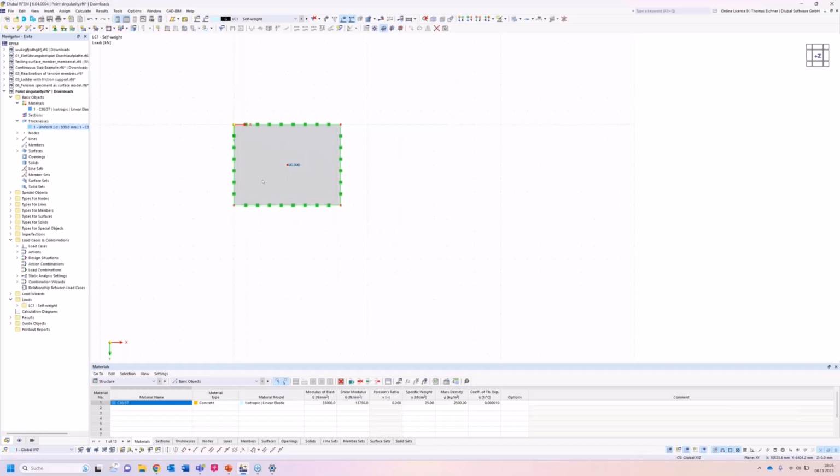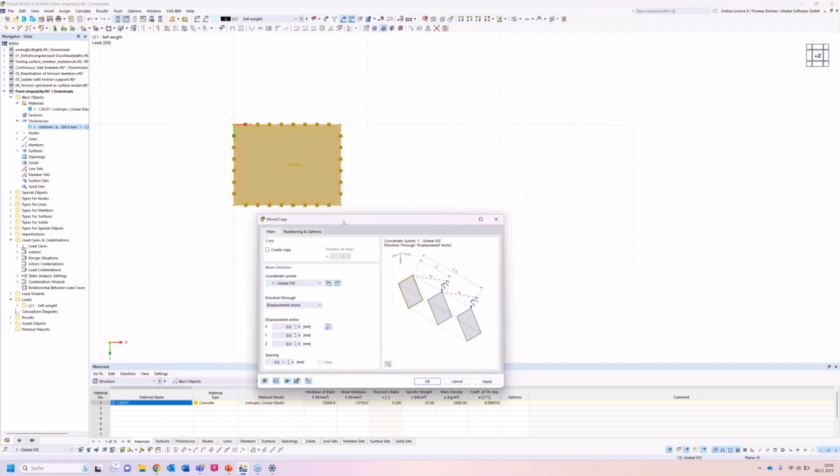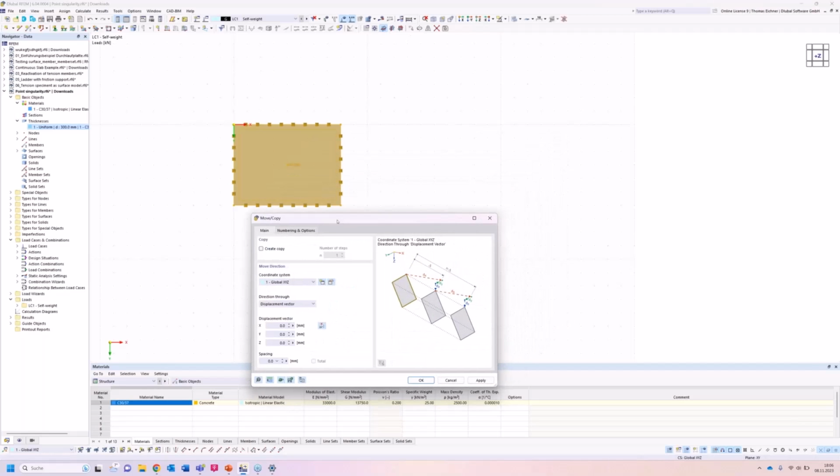And in the next step, we would do, like in the first model, the option to copy the selected objects. We want to do again one inspection for the mesh refinements in the end. So we want to have 4 surfaces with 4 different mesh refinements.